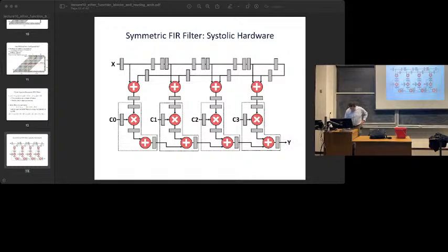So basically the modern DSP blocks are pretty good at doing things like FIR filtering. As I said, this dashed line shows you what's in Stratix 4, and it allows you to build a nice systolic FIR filter without a whole lot of extra logic. In this case, it was symmetric, so I did get some extra logic for this adder and for all these registers. But the rest of it is all hard stuff. Does that make sense?